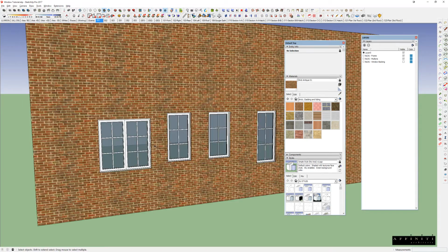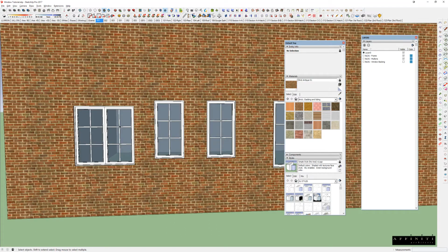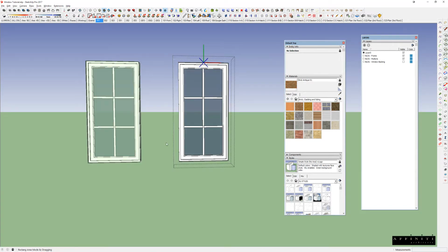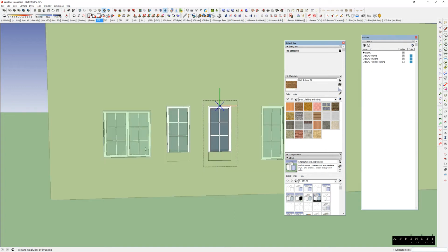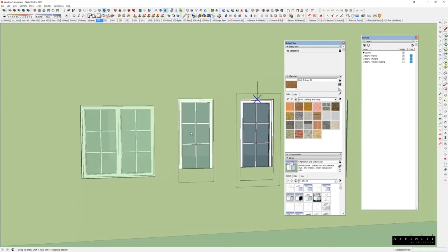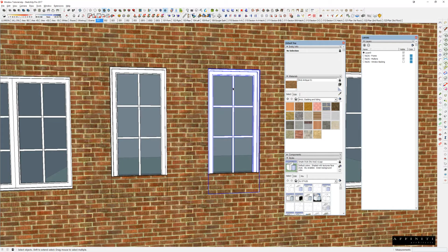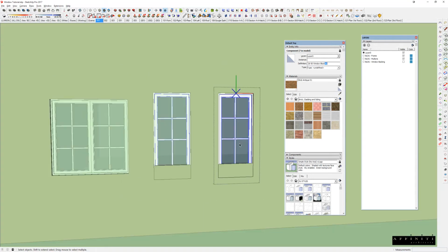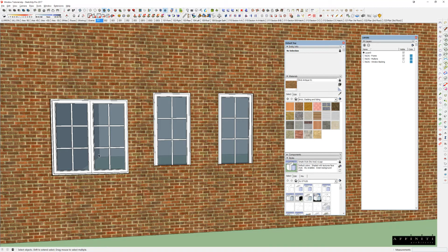It's one of these things to be aware of, that the window in and of itself is a component within a component. So now if I go inside the overall component and we're trying to stretch this, these here would not stretch. So this is still its single 2650, but this window here you can see created block #2. And this one did not adjust. And again, maybe that's what you want, maybe it's not.